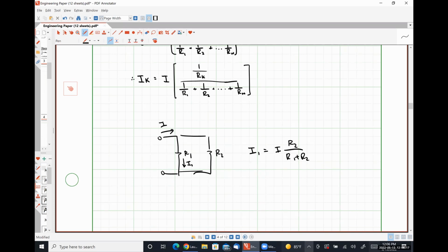Yes. So it's working on Faraday's law of induction to where effectively, when the flux through the A phase is at its maximum, the voltage of the A phase is at its maximum. And then obviously the voltage of the B phase and the C phase are at lower values because they don't have the maximum amount of flux. And as it rotates, those magnetic fluxes change, which causes the voltages to change as a function of time. And you get three sinusoids superimposed on top of each other, all delayed by exactly 120 degrees of phase separation.